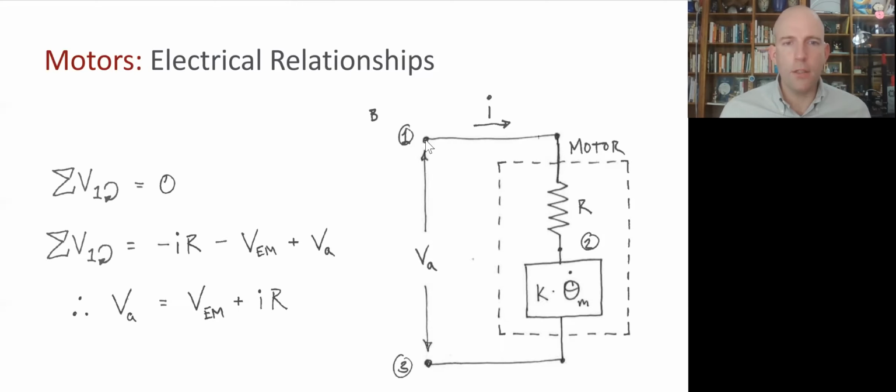So in the system, we'll model the motor with these two separate voltage drops. One is the voltage drop due to the coil resistance. And we remember Ohm's law, V equals IR. So that's this IR term, that voltage is going to get smaller as you move this way.